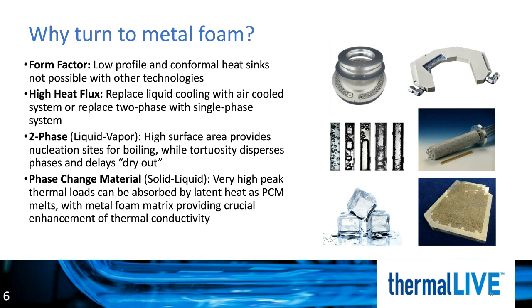Metal foam also performs well in solid to liquid two-phase systems, typically referred to as phase change material or PCM heat exchangers. In PCM heat exchangers, high peak thermal loads are absorbed into latent heat as the PCM melts, while the metal foam matrix provides crucial enhancement to the structure, increasing thermal conductivity, allowing very uniform temperature profiles throughout the melting process. Metodi will circle back to talk more about specific applications that demonstrate metal foam in action later in today's talk.